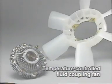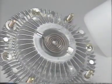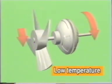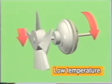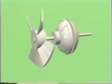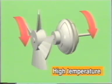The temperature-controlled fluid coupling fan changes its speed between two levels according to the air temperature in the radiator. When the air temperature is low, fan speed is kept at low level to quicken engine warm-up and reduce fan noise. When the air temperature becomes high, the fan speed changes to a high level to increase cooling performance.